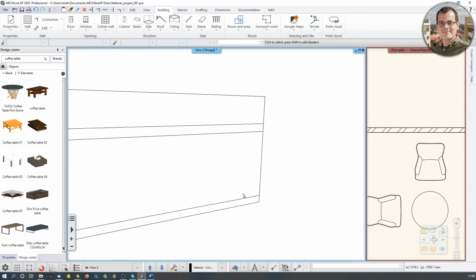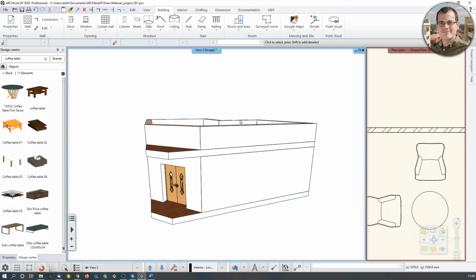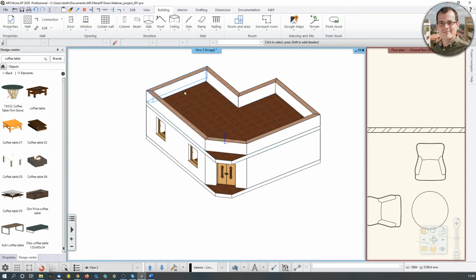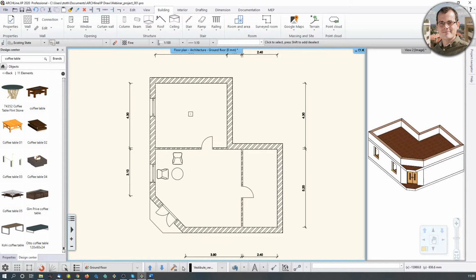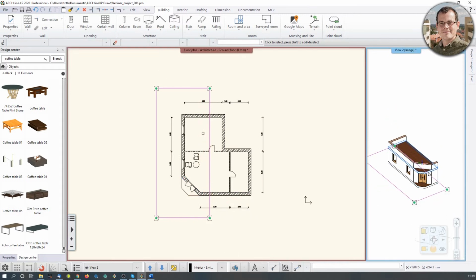There are some other things it can do on the other hand. Let's say that I want to create a cutaway model of this location. Before I do that, I click on the representation style over here and I go back to axonometry, just like that. And let's say I want to have a cut like this one. So how do I do that? I select the 2D and I click on the 3D hammer and I say create a cutaway view. I select the rectangle and then the software says I'm just going to chop this down to 2 pieces.